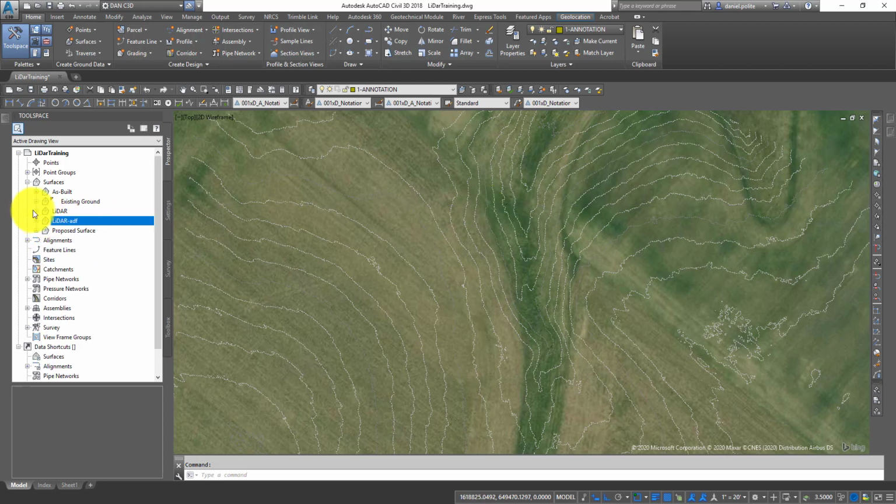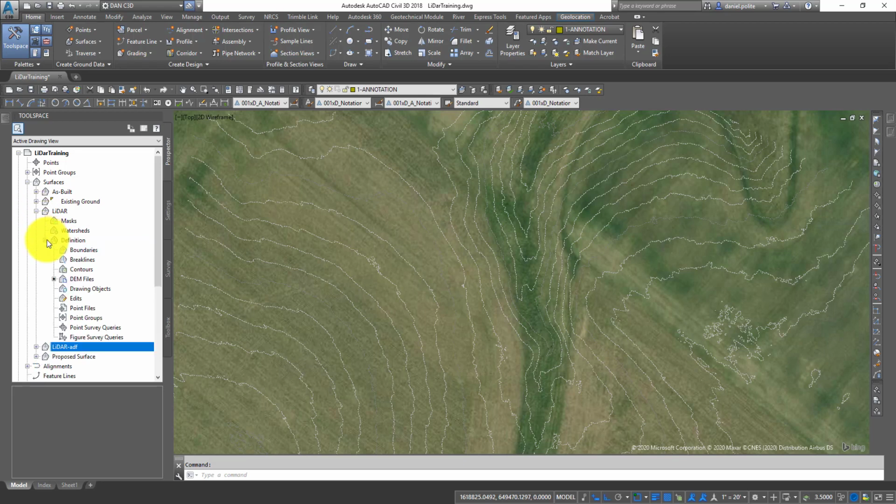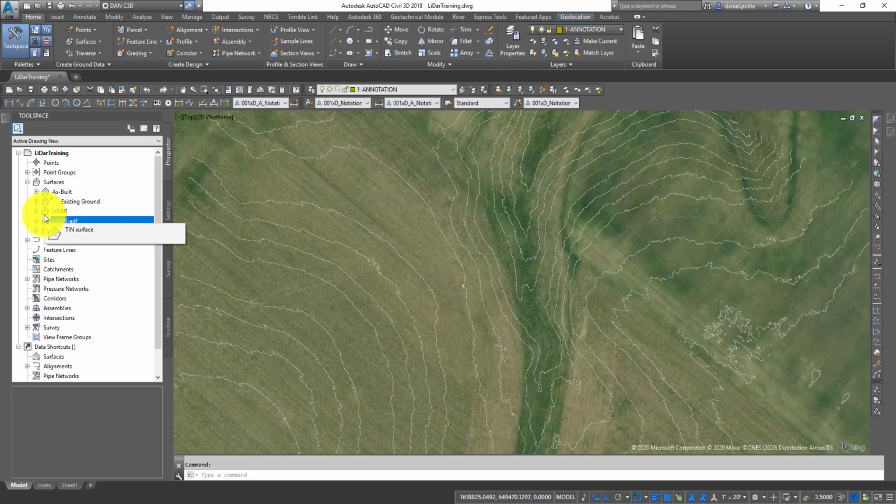Is one better than the other? Not that I'm aware of. It's just two different ways of doing it. You can do it using the ADF file that was created when you create your DEM, or you can export the data as a TIFF file and bring it in that way. The only reason I like the TIFF file is because it's one file that you can just drag and drop into your working folder and it's done.